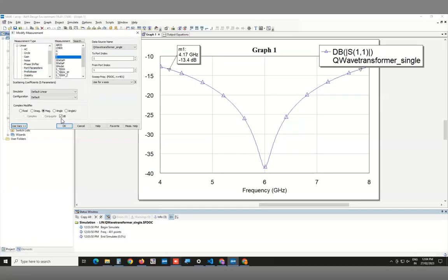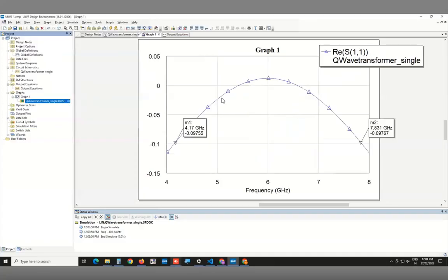The double dip is happening because the real part crosses zero at two different points, whereas exactly at the matching point, it crosses zero at only one frequency. And because there are two zero crossings, when you're taking the log of negative numbers, of course, this must be using some convention where it converts it into a positive number, basically computes the mod of the quantity and then takes the log. You get a dip because it looks like it's matched here and matched here.